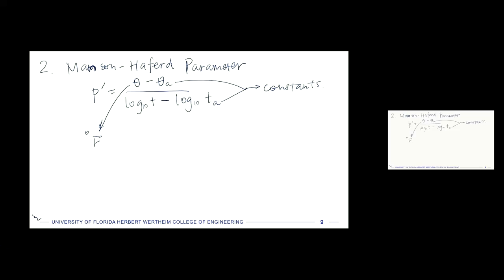But we're going to talk about this a little bit more generally, because what we really want is not this kind of parameter and then to try to have to handle stress and strain differently, but we want to be able to add this to our understanding of stresses and strains already, and maybe add on a creep strain on top of an elastic strain or a plastic strain or whatever, so that we can solve problems and say, I predict that this sample is going to elongate that much in the next 1,000 hours, which will meet or not meet some design spec.